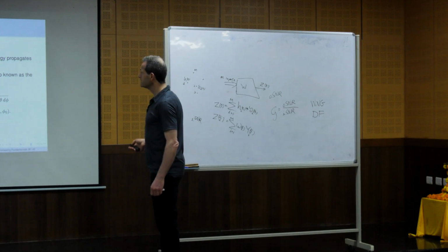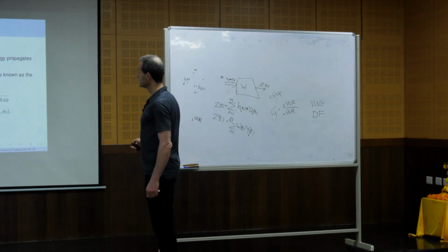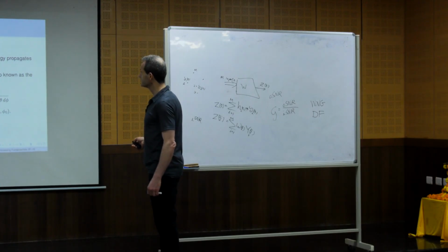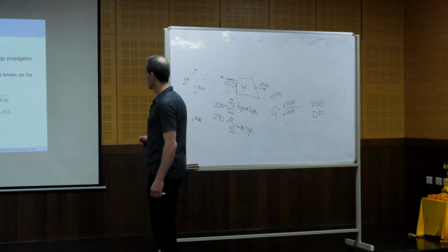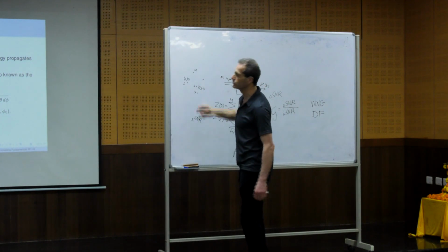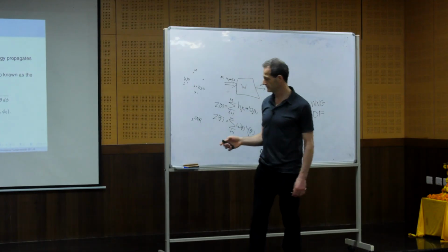So the directivity pattern for a certain direction, this is the direction of the desired source. The magnitude squared of the directivity pattern in the desired source direction, it means this is the gain of the output desired signal compared to a single sensor.